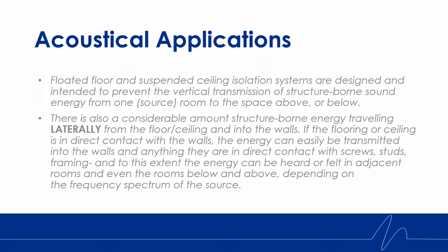So from, and airborne for that matter, we're going to focus a little bit more on structure-borne energy, and we'll get into that. But the vertical transmission of structure-borne sound energy from the source room to the receiver room, the space above or below. On that note, there's also a considerable amount of structure-borne energy traveling laterally, side to side, from the isolated floor or ceiling into the non-isolated walls.